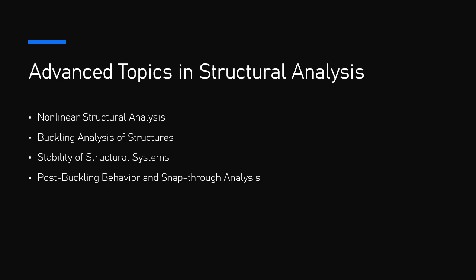Boundary condition nonlinearity, when constraints or boundary conditions change due to deformation, such as nonlinear contact or sliding. Nonlinear structural analysis allows engineers to predict the behavior of structures more accurately under extreme loading conditions, which is especially important in the design of structures subjected to seismic, wind, or impact loads. 10.1. Types of nonlinearities in structural analysis.